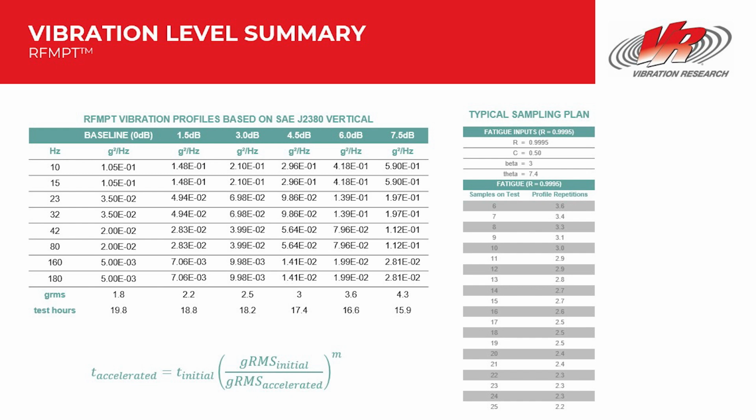For this example, I chose 6 parts on test with 0.9995 reliability at 50% confidence. And you can see on the chart at the right that that means that for 6 parts, we need 3.6 repetitions of our duration on our profile, which is 5.5, the standard time, times 3.6 for 6 parts on test, gives us the 19.8 hours that we need to run the test.